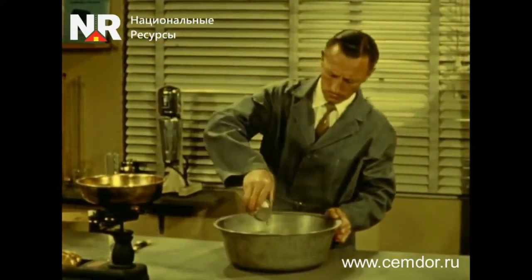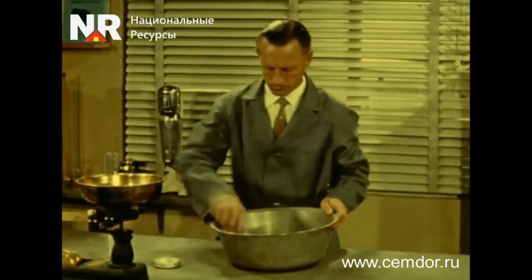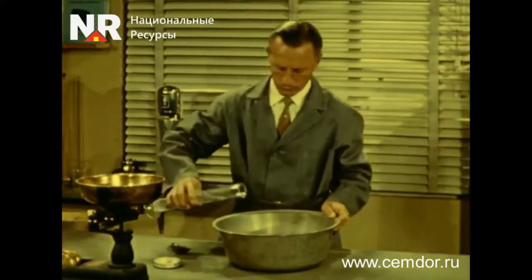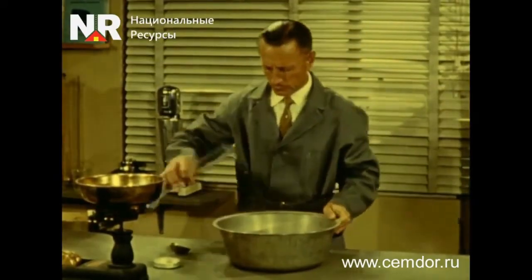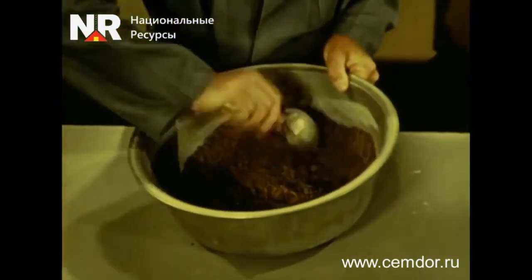Cement is added based on the required strength characteristics of the soil concrete. The amount of water needed to moisten the selected sample to the moisture content of the first test is calculated. The calculated amount of water is added to the selected soil sample in several steps, mixing the soil with a metal spatula.